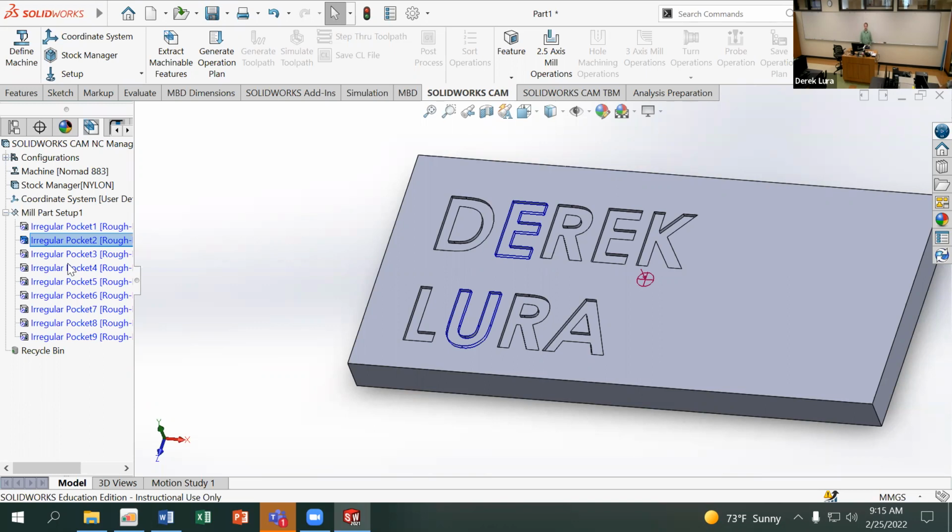When you were setting up the tool, as far as the machine ladder... Yeah, what would be the difference with one to two tools? So for ours, I've only set up one tool, so there are no tool changes. When you have multiple tools, SolidWorks will pick the best tool for each operation, right? And so that will require tool changes. On this machine, you have to manually change the tool. A lot of automated milling machines have a tool crib, which is why it's called that on the system, where it'll automatically change the tool as part of the manufacturing operation, right? In which case you don't have to do a whole lot, which is nice.